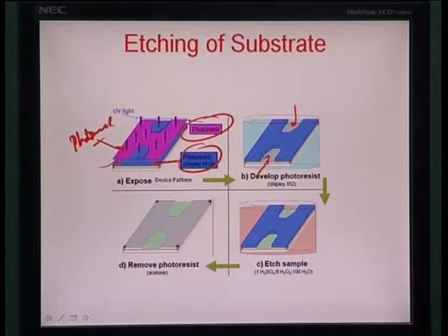So, whatever was on the photo pattern as open areas, these two open areas, have been translated into these vias on the photoresist. Light fell on them and it got debonded, so it could be removed or etched away. One more interesting factor is that it has exposed the underlying silicon surface, which was the base wafer, to etching action.